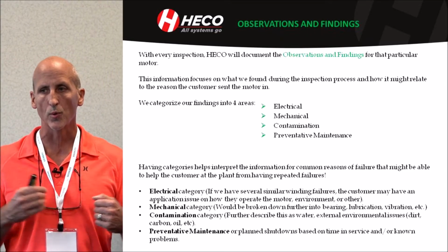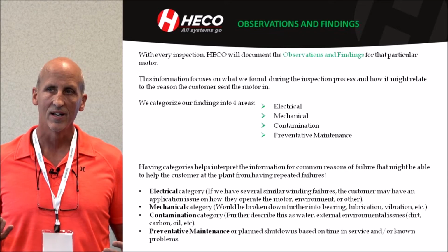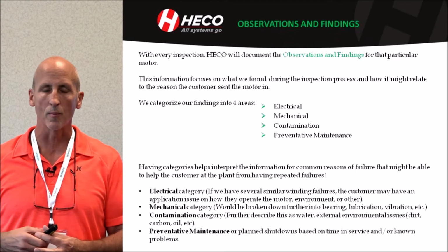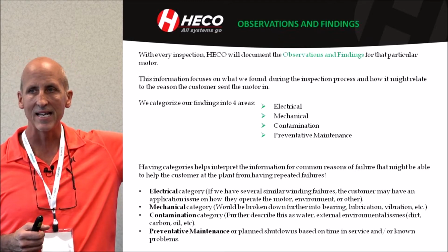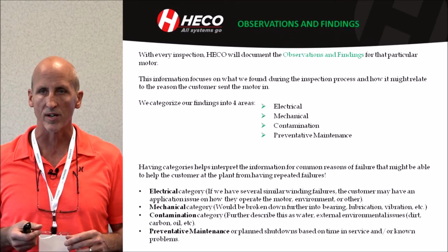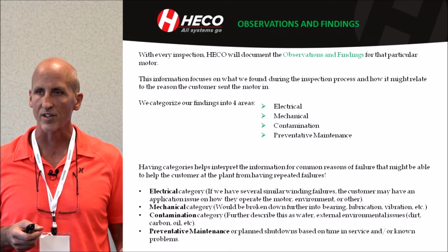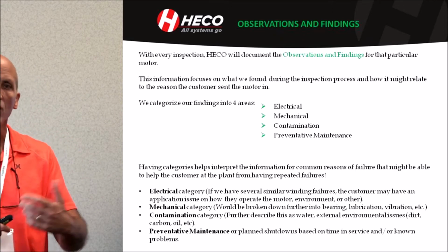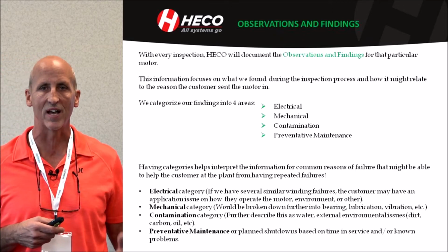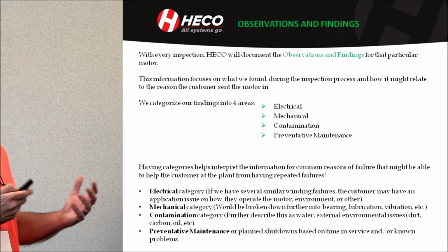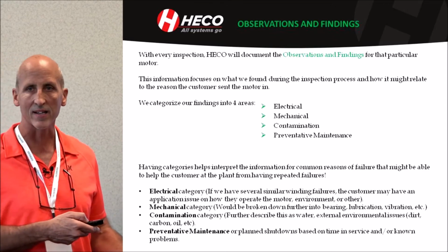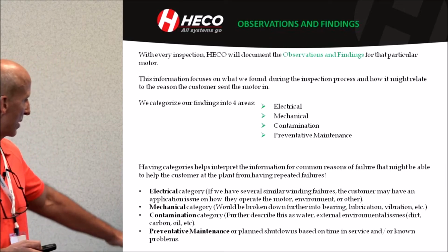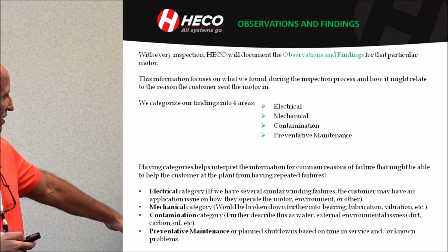identifying and categorizing, so when we have larger customers where we get more volume of work, this becomes really important because we're looking at several cooling tower motors or several ID fan motors or whatever the motor is, and we're seeing a similar failure. Hey, that rotor failed this way. I wonder about the sister motor. Lo and behold, that one might have the same type of failure mechanism. So being able to identify that, offer that back to the customer to plan for inspection, but categorizing it properly.